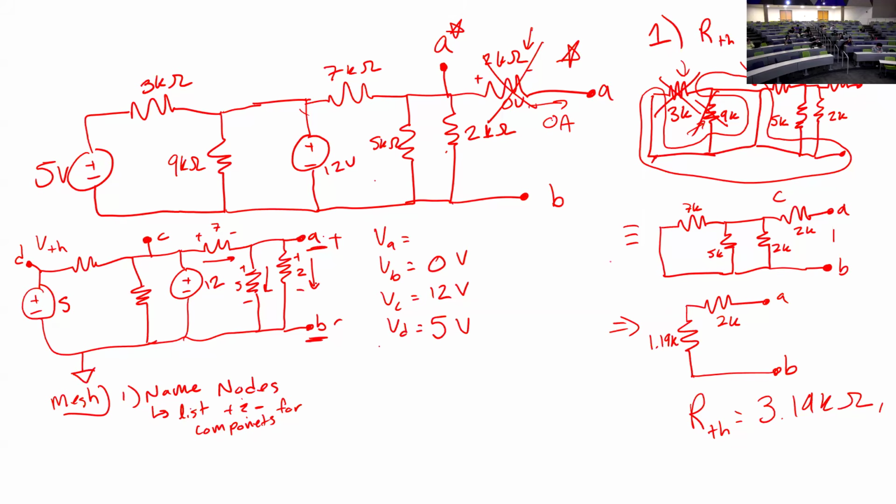So solving for VA here, there's 2 ways to do it, and I'll do it both ways. It's purely whichever one makes the most sense to you quickly. The first one is with mesh analysis. So this is using KCL, which is the sum of I in is equal to the sum of I out. We're going to use KCL to be able to solve this in a way that is quick. So at this node A, coming in, I have this voltage across this 7 kiloohm resistor.